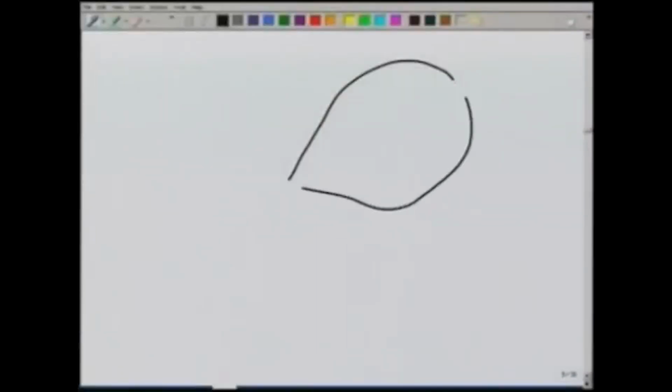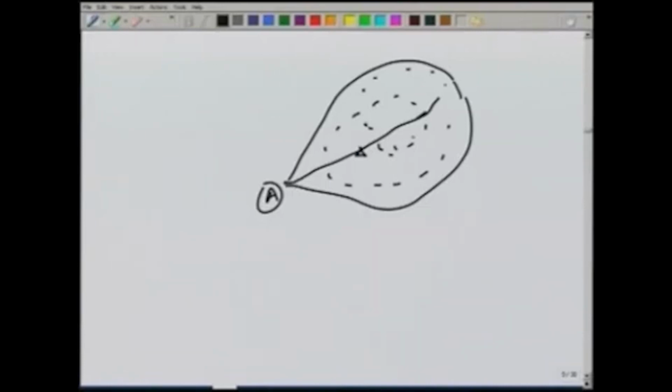So, over a certain area, let us say this is the catchment area, a river originating here and moving to the point A. And now, let us suppose that there is some rain over this entire area. We will assume that the rain is of uniform intensity. So, the rainfall which occurs, its hydrograph can be plotted as intensity versus time, and it may be, let us say, uniform intensity for certain duration d.